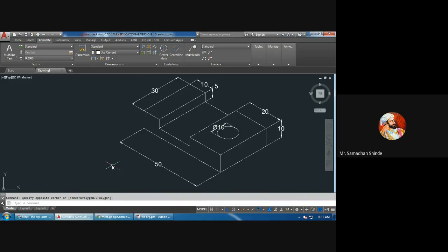Here also it is the same thing. Whatever drawing we have drawn, here one view direction is there at the corner. So the top plane it is showing, meaning on a 2D plane we have selected three different axes. Which three different axes? One is 30° towards the right hand side, one is 30° towards the left hand side, and one is vertical. On a 2D plane we have selected three different axes. That's why the visualization of isometric drawings is 3D. Actually, isometric drawings are 2D drawings only.